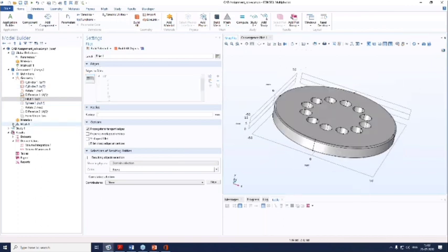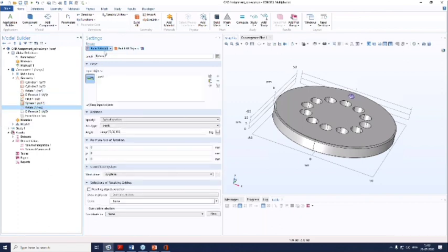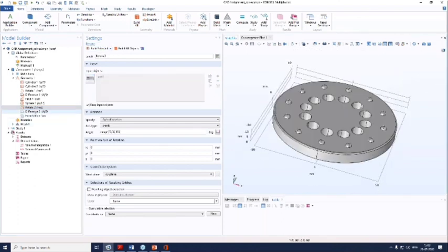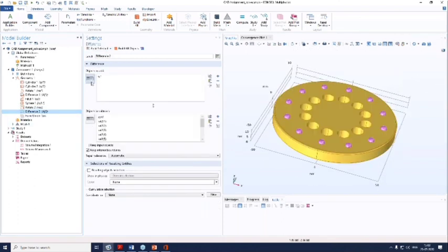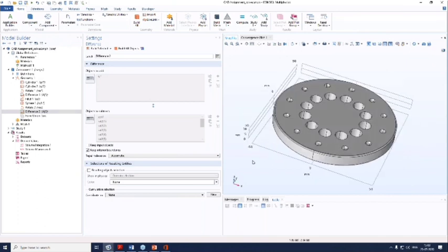So with this, you can see that this is the fillet that we have created. Then we have drawn the spheres. The first sphere, again, we have created a circular array with the rotate feature, and again from this filleted object, that is this circular disc, we have subtracted these spherical array objects, and this is how you will end up having the final geometry.